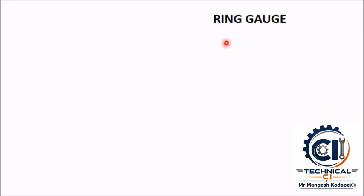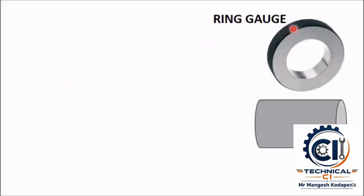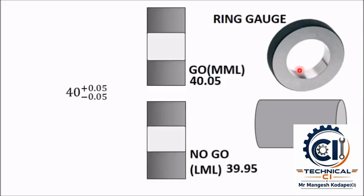One such limit gauge is the ring gauge, which looks like this. This is a ring gauge, and it is used to check whether a particular shaft is acceptable or not. Ring gauges are used in a set. There will be two ring gauges, one called the go gauge and one called the no go gauge. I want to measure this shaft diameter, with the same dimension, 40 ± 0.05.